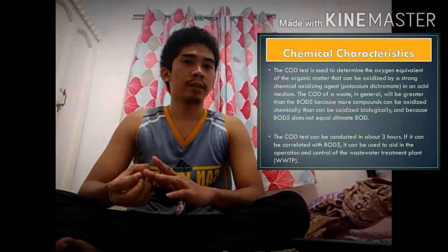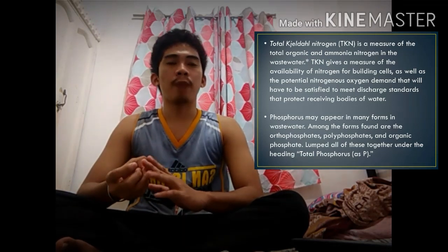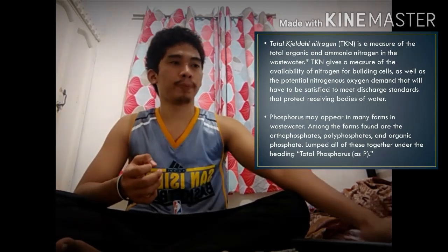It is also said that domestic wastewater contains different chemicals. For example, phosphorus may appear in many forms in wastewater. Among the forms found are orthophosphates, polyphosphates, and organic phosphates. Lump all of these together under the heading total phosphorus.